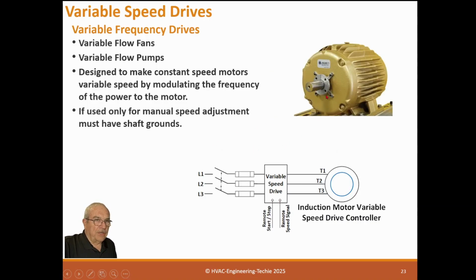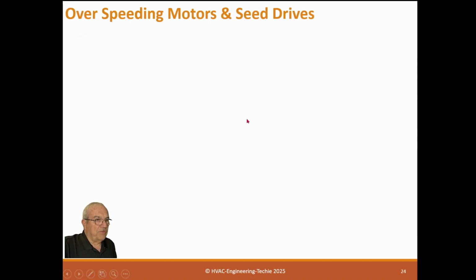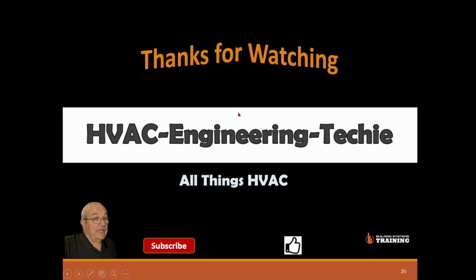And this is a little ring on a motor, and you see that it just grounds the shaft, and that means that motor will be protected no matter what it does. A lot of people specify a ground ring on every VFD motor. Available in 1, 2, or 3 phase motors, and that's basically it for electric motors.